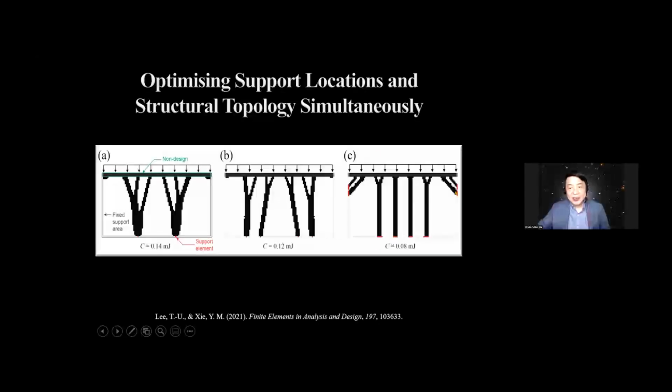This kind of technique is quite useful because when you design bridges, sometimes you may not be allowed to have support at the bottom, the horizontal line, because the valley might be very deep. So you can only put the support on the 2 edges of the bridge. In that case, we can only specify the candidate support points on the 2 edges. Then you wouldn't have these 4 columns. So this kind of algorithm would be quite useful for you to find the support conditions when you design bridges.